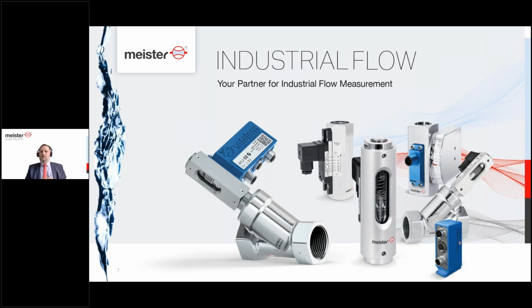Because later on, as the signal information goes along the automation pyramid from the very bottom, from the signals over the PLCs and SCADA systems and human machine interfaces until software programs, it will end up anyways in digital systems nowadays already, where finally a computer is managing all these sensors and information. So the earlier the digital information comes into that chain, the bigger the advantages of having a reliable signal without dealing with the disadvantages of analog data transfer, which is not as reliable, not as accurate.